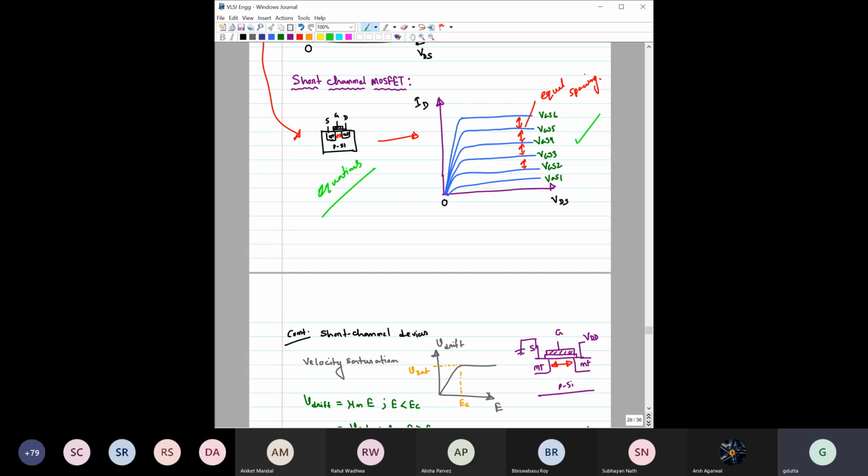Their role is that you give any new device, and they will give the mathematical equation for that particular device, so that its characteristics can be represented by a mathematical equation. Many times it is physical. Physical means whatever equations you are giving have some physical significance. If you change the gate length from, say, 180 nanometer to the next step, 150 nanometer, then that equation also holds for the next technology node. That is called physical modeling.